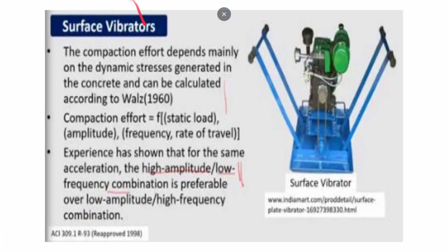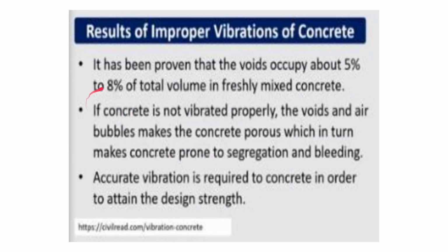So in surface vibrator, for a constant acceleration, high amplitude low frequency is a better combination than low amplitude high frequency.